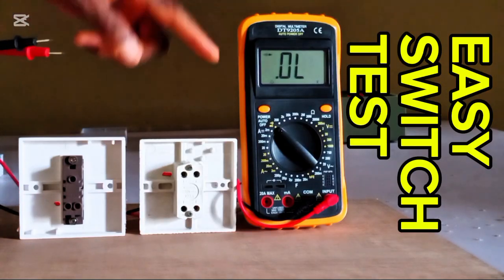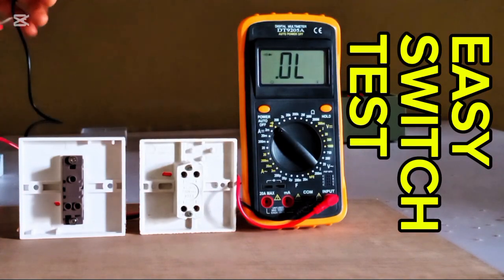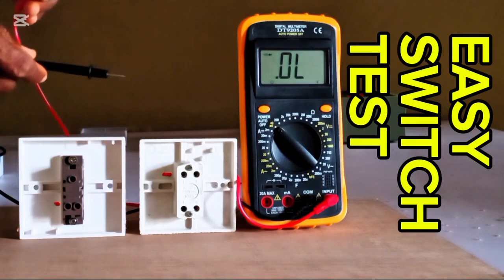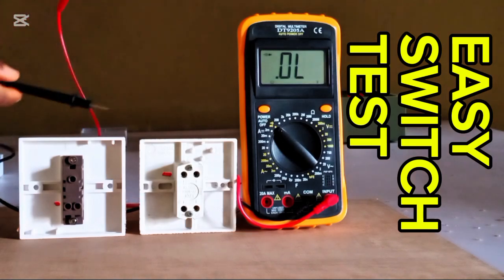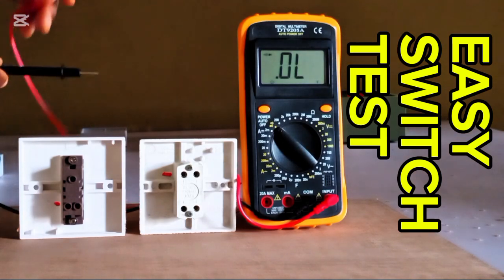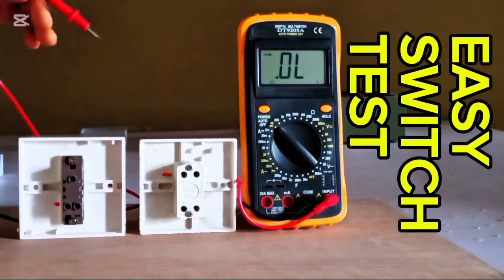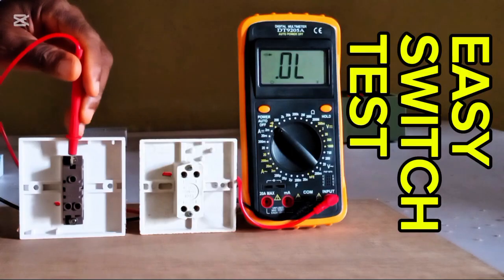All right, I have set the meter on ohms, so it will be able to read the ohms value for us and at the same time beep, or make a sound for us to hear. The test we want to conduct is called a continuity test. So let us begin with the two-way switch.